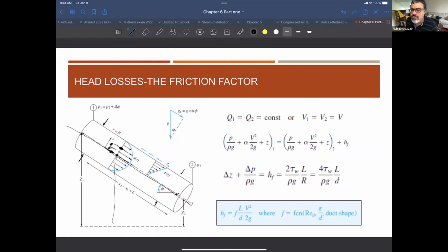No, don't be sorry. I'm just saying, try to remember this discussion. I know what you mean by elevation, but think about it: the elevation is not across the pipe cross section. When we're talking about elevation and potential heads, we are talking about a point in a pipe and another point downstream on this pipe, never across the pipe cross section.